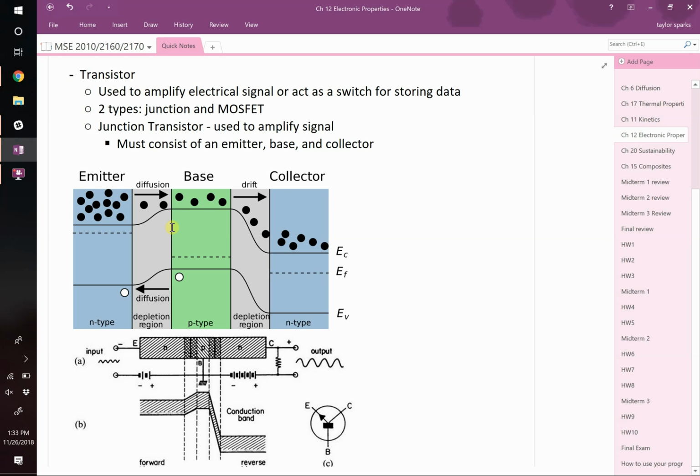Typically, there are different ways. There are some that rely on the pressure variation, but they're not the best ones. The better ones rely on magnetic strings. If your strings have cobalt in them, they're slightly magnetic. Therefore, as they vibrate, it creates a very small current as they move, and you have an electromagnetic sensor, right? In any case, your signal comes in and it's quite small. If you just took your guitar and plugged it into a speaker directly, you're not going to get a lot of noise out of that because the pickups don't generate a very big signal. A transistor is something that can amplify that signal, right?